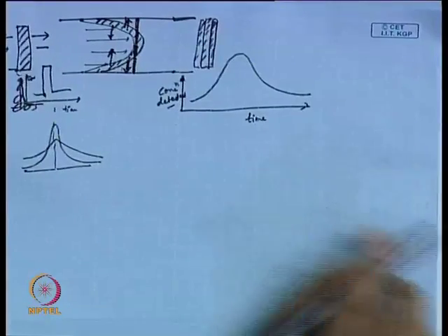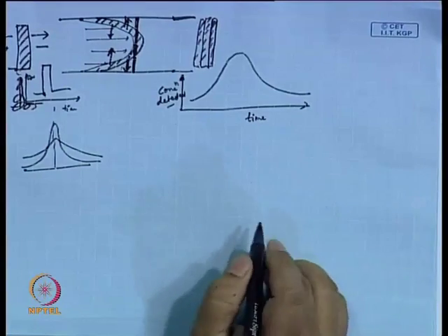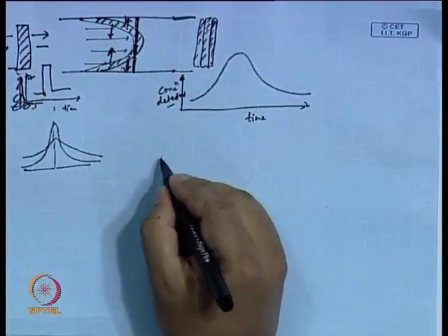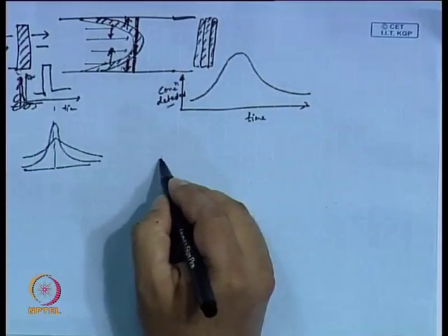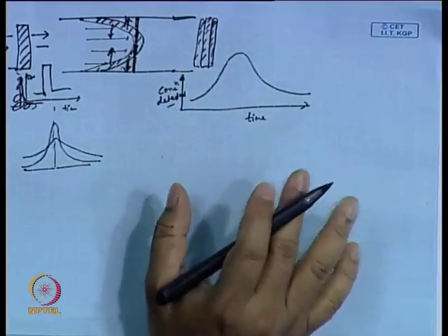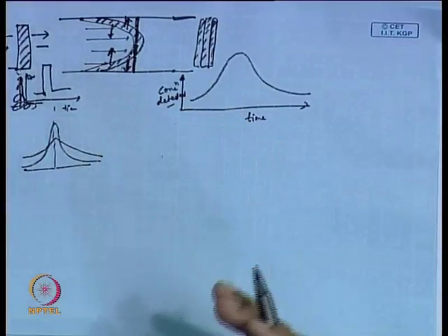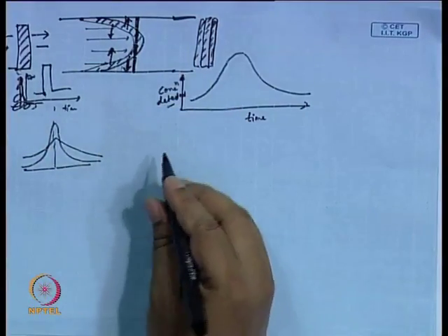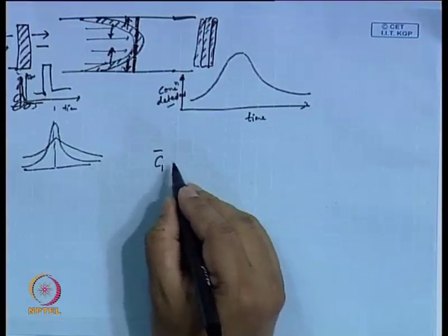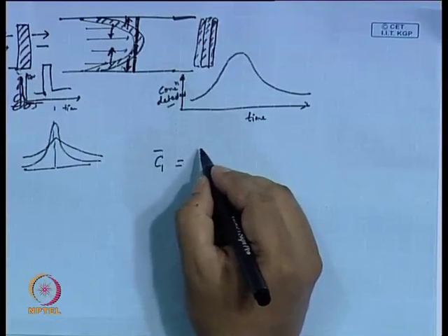This process is referred to as Taylor dispersion, and this is something you have to be very careful with when you are working with laminar flow in a channel which has a very small transverse direction. Now, let me give you the final result, what you get as a concentration profile. I will try to come up with the governing equation and boundary conditions, but first I would like to give you the final expression.